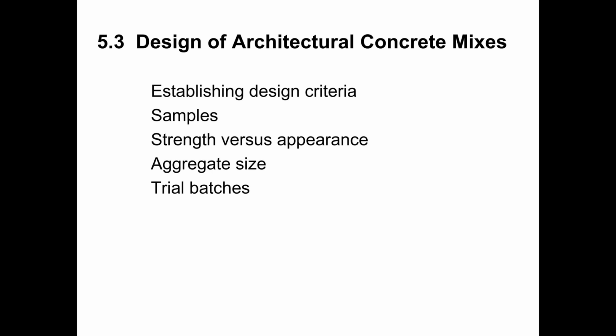And then a third sample that's in between those two that gives the architect an idea of day in, day out, this is what the panels are actually going to look like. All right, so in establishing that appearance approval, we don't want to just send a perfect finished sample because then we may be putting ourselves in the position that the owner is then going to expect all of the panels to look perfect. That's not realistic.